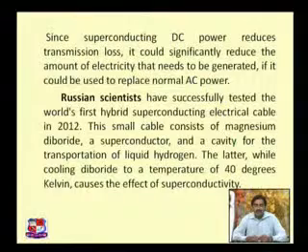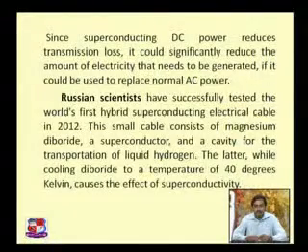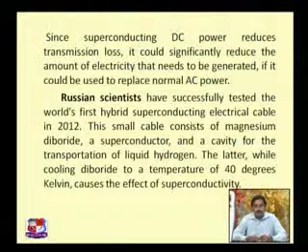For making such kind of hybrid superconducting grid, they have made a special kind of conductors, or we can say cables, in which they were passing liquid hydrogen, and with the help of the low temperature they were able to convert the conducting wire within the cable to a superconducting state, and due to that they are not offering any kind of resistance. And for that they have generally used magnesium diboride. This is a compound of magnesium, and it offers superconductivity at low temperature.